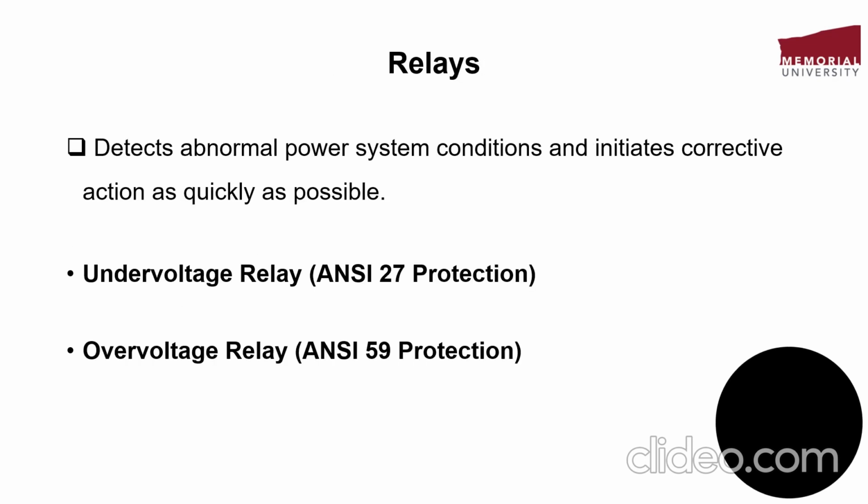So in this main project, basically I have used two relays which will detect the undervoltage and overvoltage conditions, and they will trip a control circuitry or a circuit breaker which will disconnect the load from the power supply to prevent them from any damage.